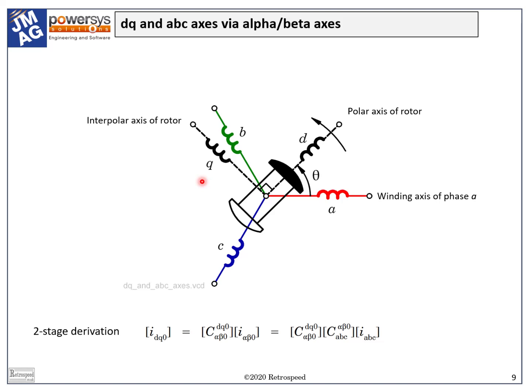In the steady state, the currents ID and IQ are constant in Park's dq frame, while the space vector components ISD and ISQ are constant in the dq reference frame that we defined to be rotating in the complex plane. Only the orientations of the two dq frames are different. In Park's transformation, the dq frame is locked to the rotor, but the space vector dq frame can have any orientation we please, including, in the case of the synchronous machine, the same orientation as Park's dq frame.